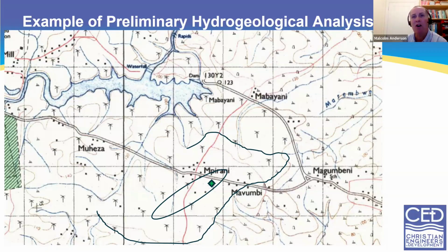And the reason I know it's the top is because here I've got streams discharging from this 120 in that direction towards the north, also to the southeast, and also to the northeast. So that means this must be a local groundwater high.